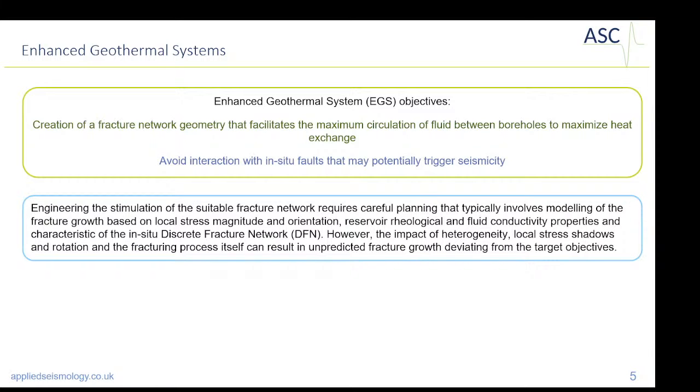So engineering the stimulation of a suitable fracture network requires careful planning, and typically this involves modeling fracture growth based on known local stress, the magnitude and the orientation of this local stress, knowing the rheology of our reservoir and the conductivity properties of our rock. And all this is summarized in getting a good understanding of our in situ discrete fracture network.